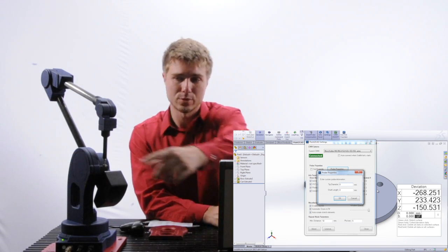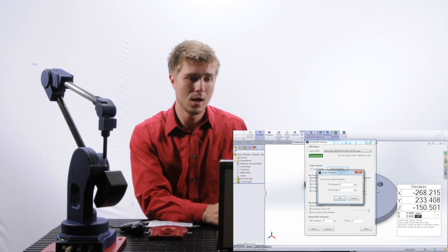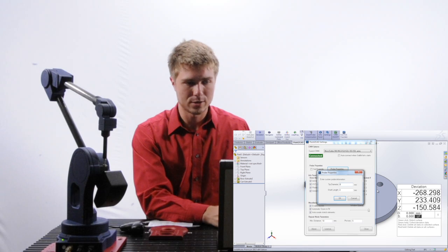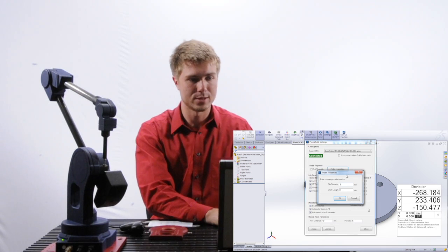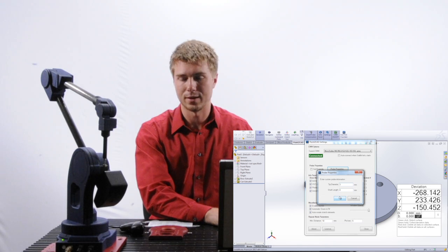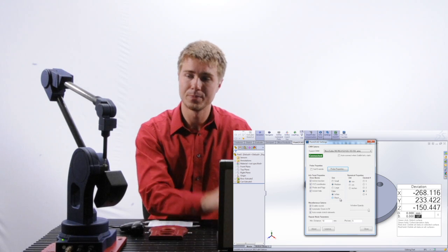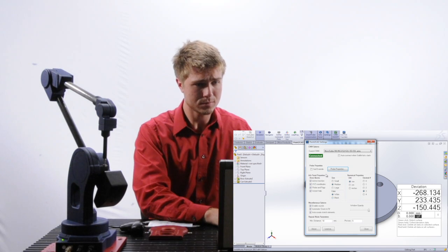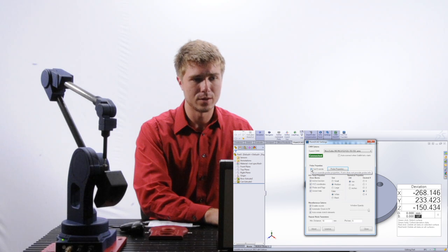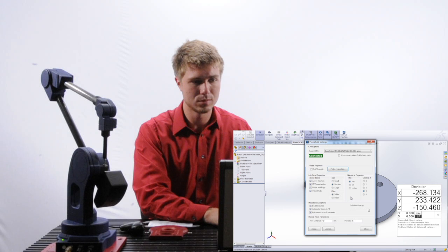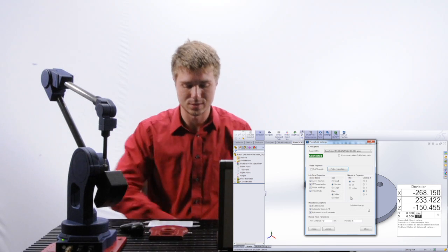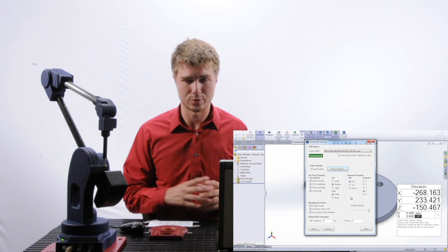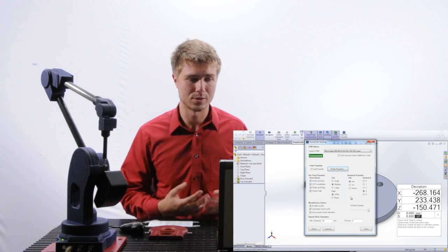and the reason why is because we're using a 3mm probe to create this, but we didn't put in any tip diameter. So for the standard microscribe, you want to put in a 3mm tip diameter and no shaft length. So once we put that in, we'll be able to reverse engineer our part in the correct manner. You can also go in and do some inspections inside of Muse to find out the true diameter of your probe tip, and also do some offsets.